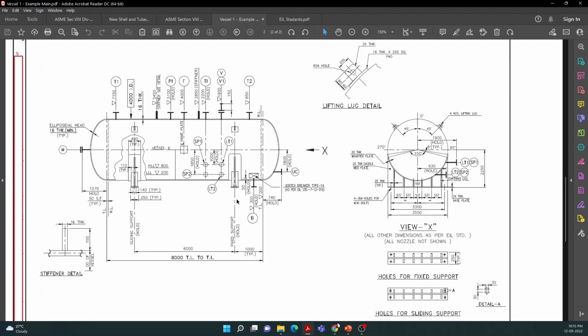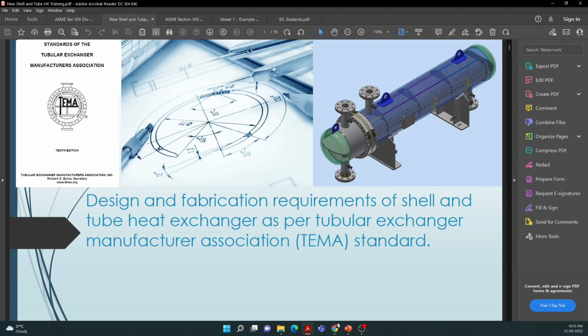Now regarding heat exchangers, there are a lot of questions, like what type of heat exchangers do we cover. There are basically shell and tube heat exchangers which are covered as per Part UHX of ASME Section 8 Division 1. So we cover that part. See, for a heat exchanger, here you can see in this image, the other parts are dish and shell, nozzle, flanges, body flanges according to Appendix 2, shell, dish and saddles. All are the basic ASME. Then there are tubes. These will be designed as per the ASME usual rules.